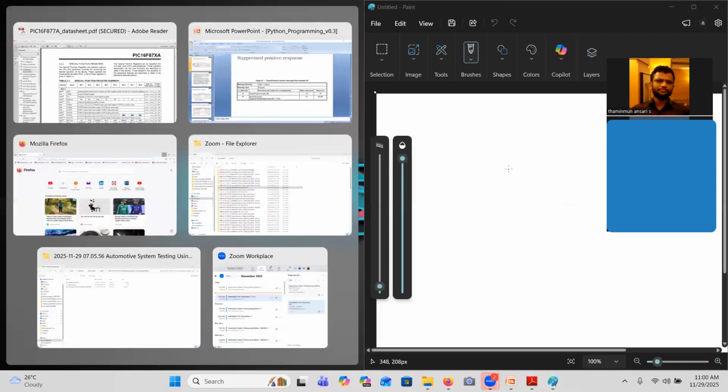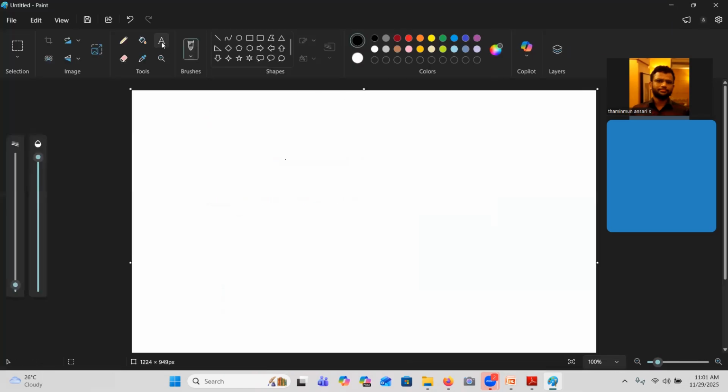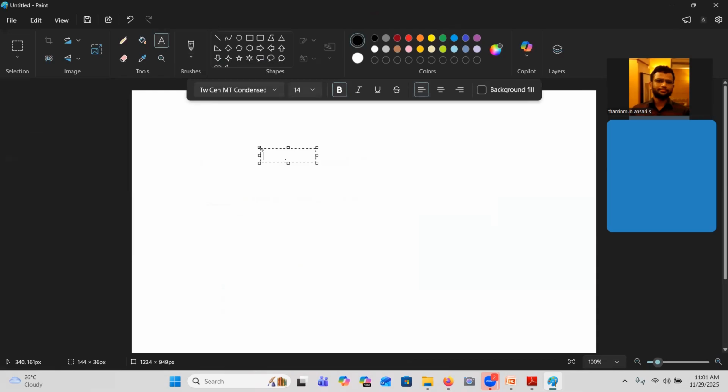use that as an input pin or output pin, for any pin in that particular register. There is a register called TRIS: TRIS A, TRIS B, TRIS C, TRIS D, TRIS E, like that. For each port, there is one dedicated register.